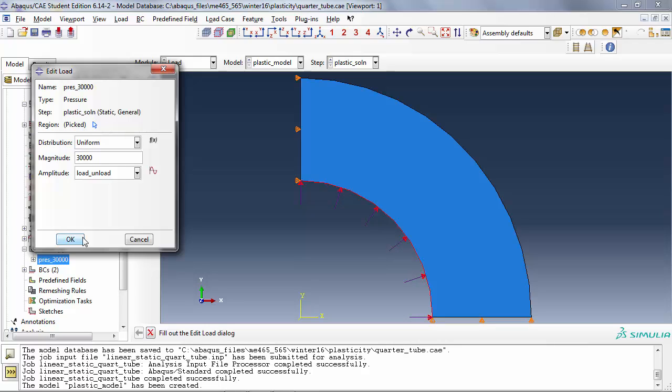Yes? Before you said we choose a load of 1. Do we do that? You can either do it here or in the amplitude. So in this case, I define amplitude being 1. Okay. The load gets multiplied by that. I'm still retaining my original load. You can define amplitude being equal to 30,000, but then you have to come back here and change the load to what? 1.